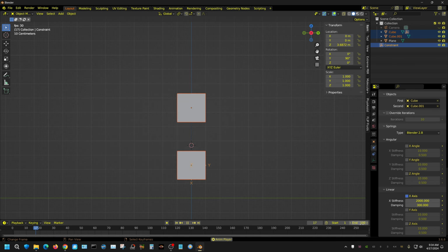That's more realistic of what I would expect from a monster truck suspension system. Of course, every time you change something, like the weights of this cube right here, it's going to change the numbers or the settings you need here. Now the settings I have on the x-axis here, because you can see the x on this constraint going up and down, right? Now these same settings that we set here can be set for the y-axis, z-axis, and then rotational as well.